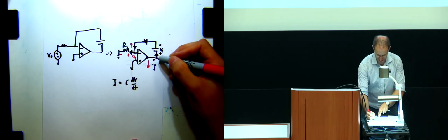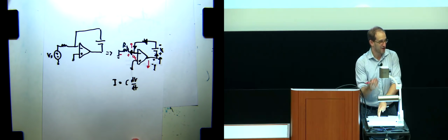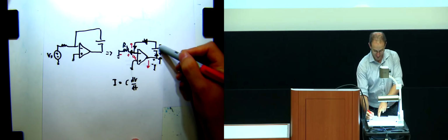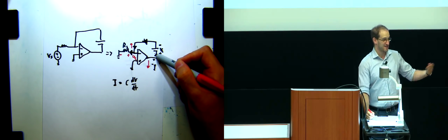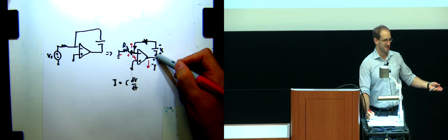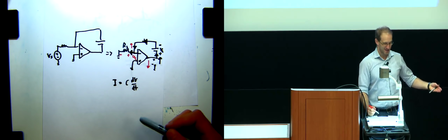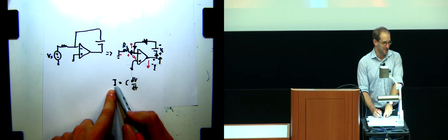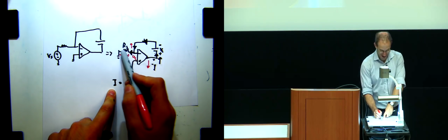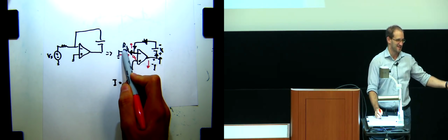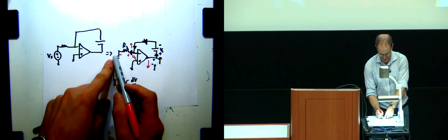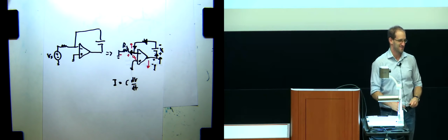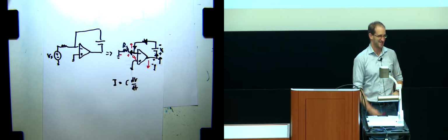Okay. So the logic or the argument that I'm following here is to say, well, if this moved, that means the voltage across the capacitor also had to change. Right? If the voltage across the capacitor had to change, that means there had to be current flowing through that capacitor. If there had to be current flowing through that capacitor, that current has to flow through the resistance. If the current flows through the resistance, just by Ohm's law, U2 also has to change. Does that make sense?